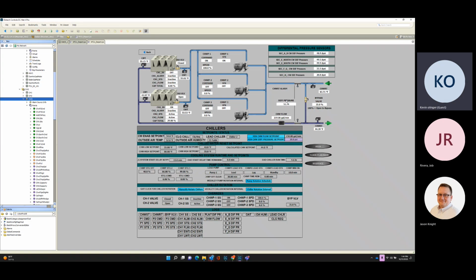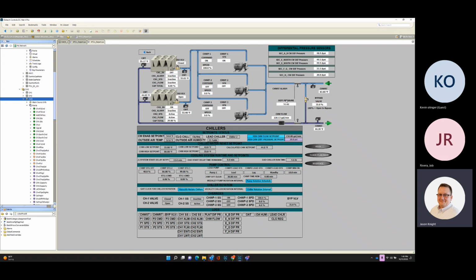Because it just seems very inefficient to have both differential pressure variable volume pumps with a bypass. Yeah, because if you've got a flow meter and you're maintaining flow, you don't need the bypass. You have to push it all the way through the whole building, but right now using that bypass just kills energy. It just seems very complex and redundant. Yeah, I mean, at some point, it always takes the path of least resistance. Well, it always does, period.